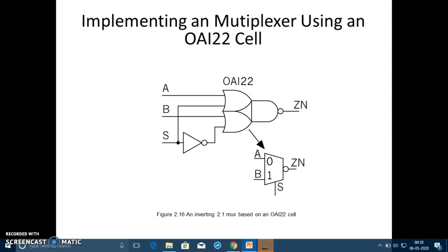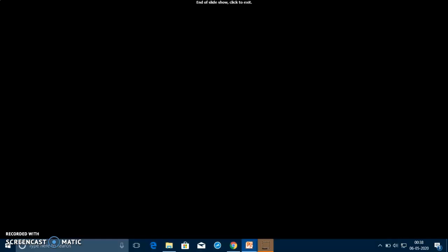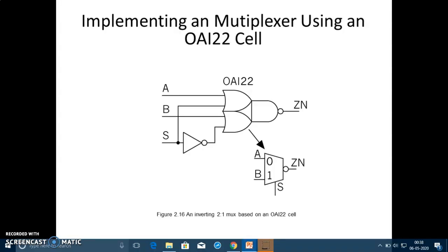Logical effort is the input capacitance of the gate divided by the inverter capacitance. We get logical effort differently for the inverter, NMOS, NAND gate, and NOR gate. Parasitic delay is the delay from the gate's total diffusion capacitance relative to the inverter's, that is, the total capacitance of the devices connected to the output node.